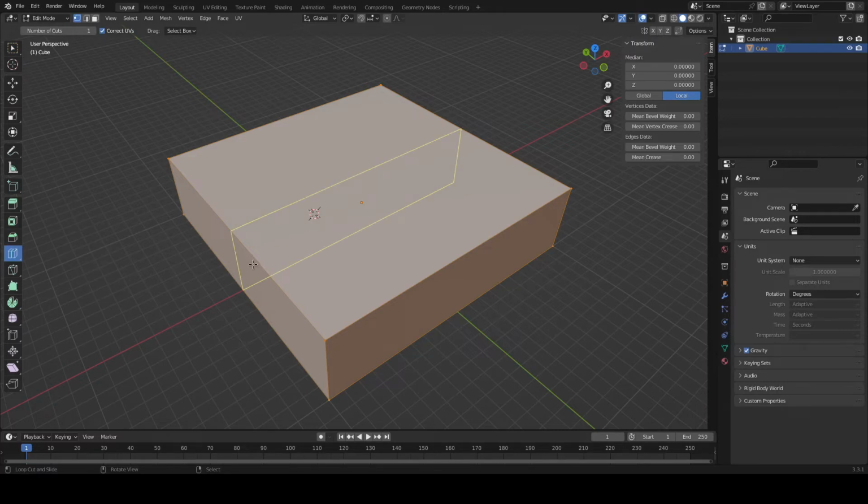And you can see that the loop cut tool creates these outlines that sort of show up. And just depending on where you hold your mouse, that slice line will show up in a different place. So the trick about the loop cut tool is that once you can see that outline, you use the left mouse button to click, but you hold down that left mouse button.